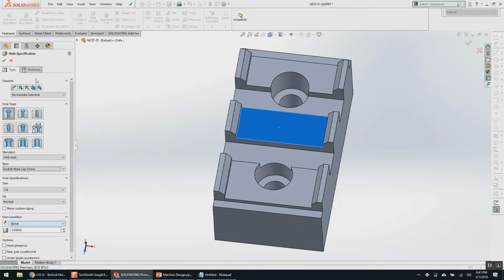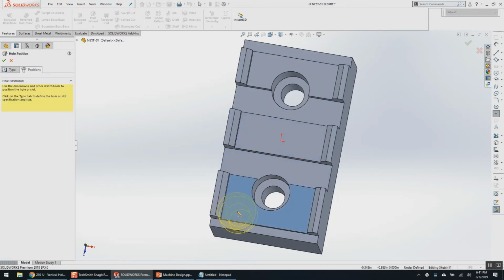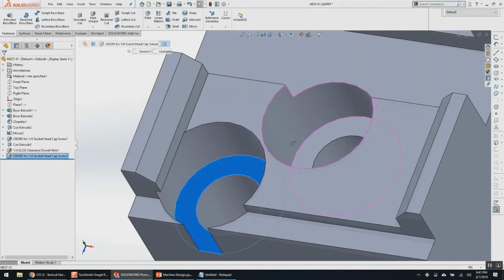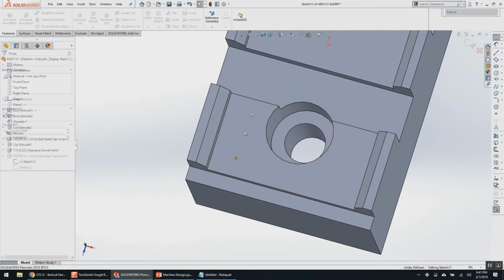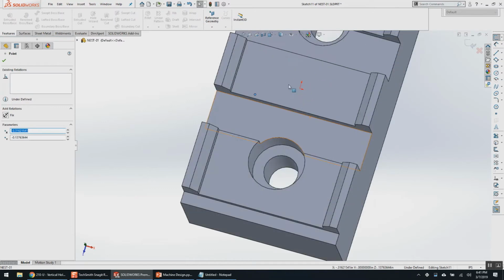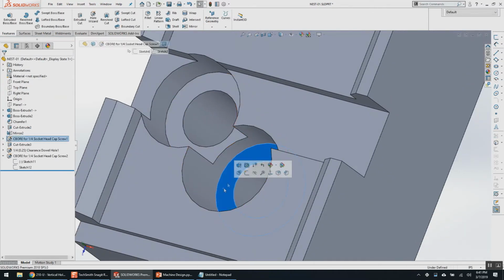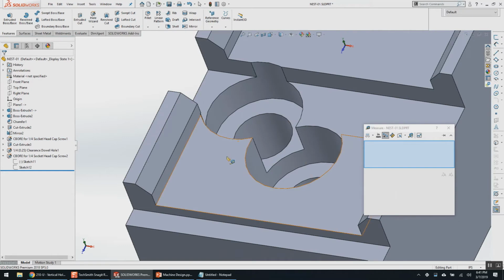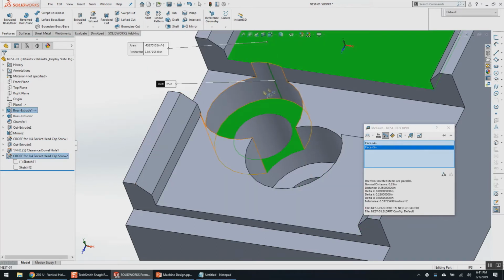The disadvantage that I have with that, here's what the software is saying. If I pick the top surface and I want to counterbore here, there's not enough distance from here, so let me try that again. If the counterbore is, let's say, here, we'll put it right in the middle. There's not enough distance from here, so I need, what is it, 1/4 inch? So I need 1/4 inch to bury the bolt head. And if you do it wrong, you're only going to have less than 1/4 inch, which is a problem.